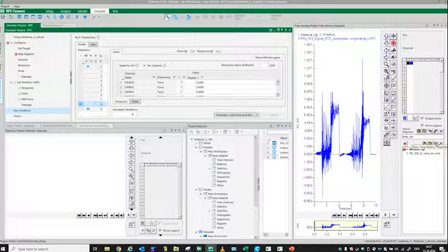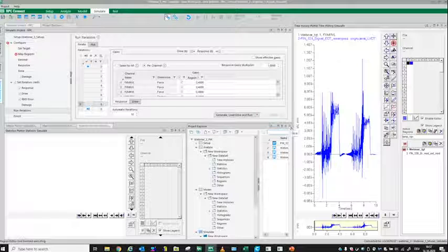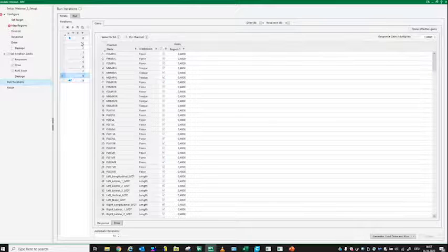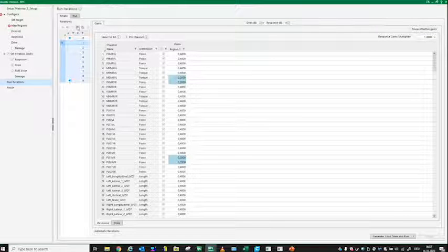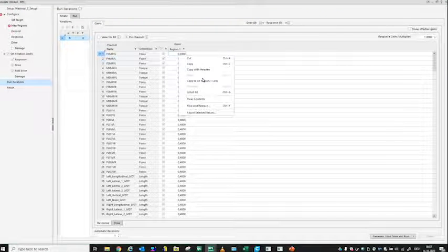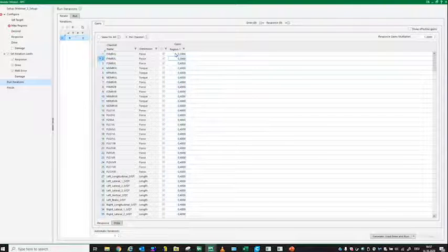Okay, two other questions that I can see here quickly. One, will the gains also be stored if the gain scheduling is not used? So if they only enter gains step by step? Yeah. We can go through an example here. I remove these here, and then I start with 0.2 for all cells. I copy them to all cells here. Next step would be 0.4 here, 0.4. And then the next step will be 0.6. Let's go for that example, 0.6, 0.6.